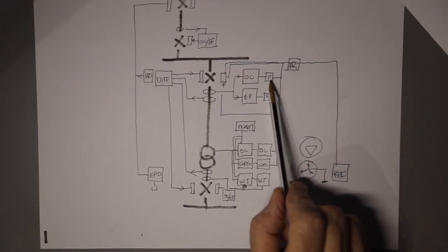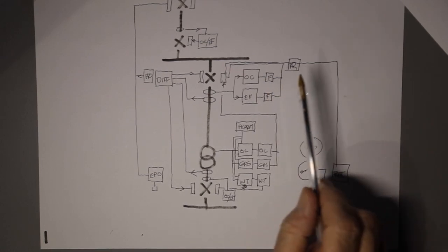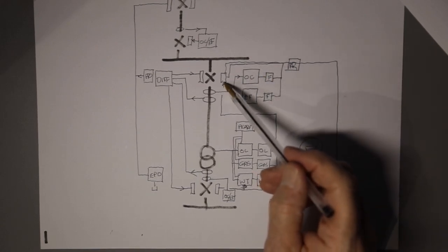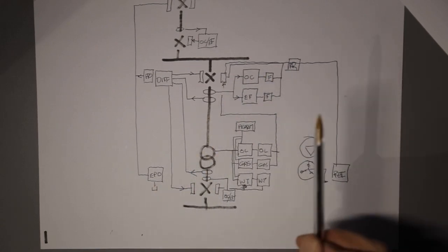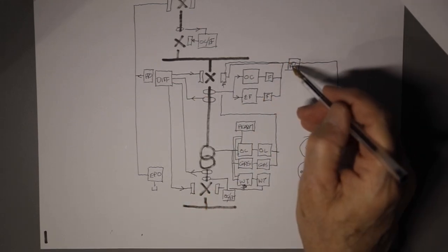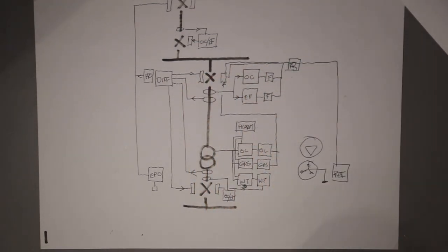and supposing you had an overcurrent or an earth fault or a differential or any other fault, you wouldn't know what had happened. So we put the flags in like here, then we can actually see a mechanical device, and we have to reset that. And it's extremely helpful.